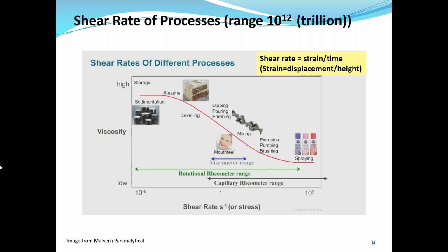Do you want to gap a particular gap thickness, say 1 millimeter, or do you want to place a certain force on it? I would probably think with that kind of material, you want to go with a particular force, because it's kind of like a polymeric. Some of the bioengineered polymeric materials we've looked at, they can tend to differ greatly by the thickness. So.